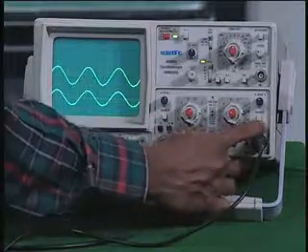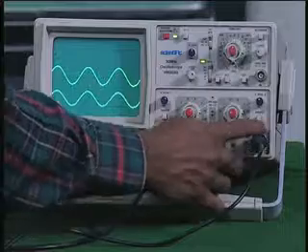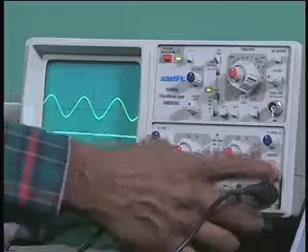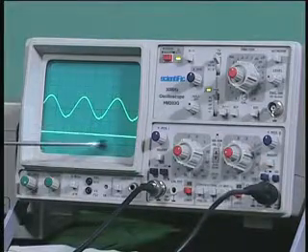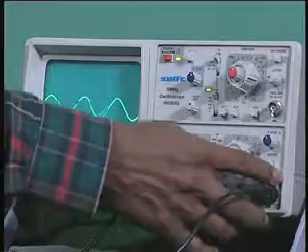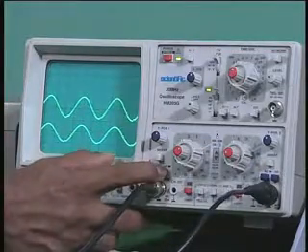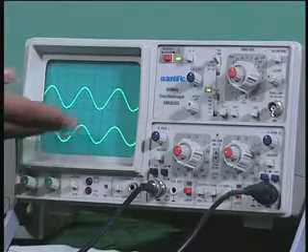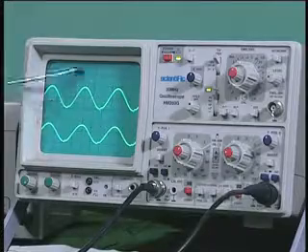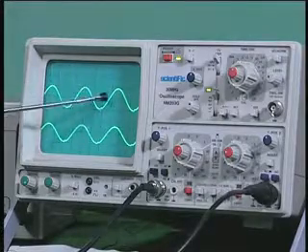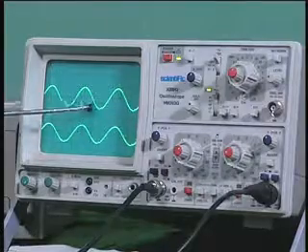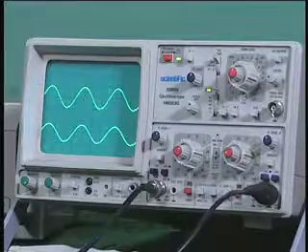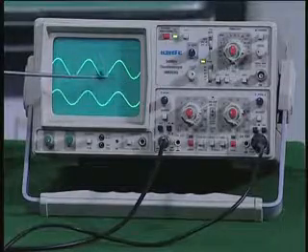Whereas the same thing if I do for the lower signal, you can see that there is no DC there. Therefore, when I put DC coupling I get only a straight line, that means there is no DC, everything is only AC, whereas in the top one you see all of them are AC, but with reference to a 0 line which is at the bottom, and therefore it is a varying DC, sinusoidally varying DC, all with reference to this reference point. Therefore it is positively clamped, that is what we mean. So this is the way to identify the DC clamping here.